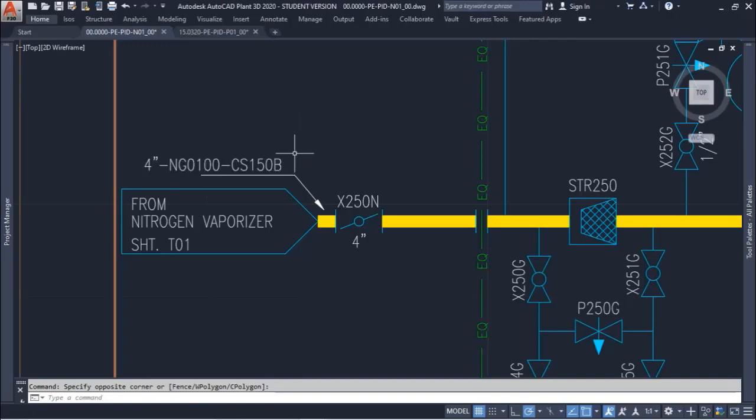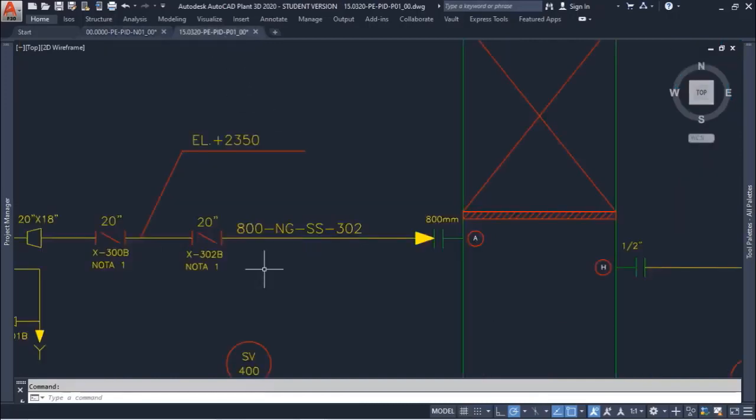Once you get familiar with P&IDs, you start understanding the line numbering for any kind of P&ID, but the correct way to know what represents each information in line numbering is consulting the instrumentation legend and symbols of your project. And just to compare with the other project, let's see how it is the line numbering. In this case, you can see that we have a similar structure